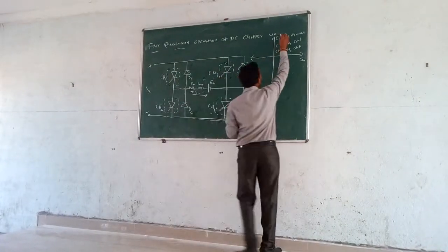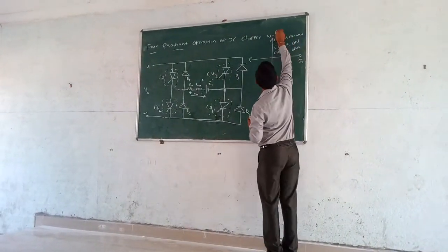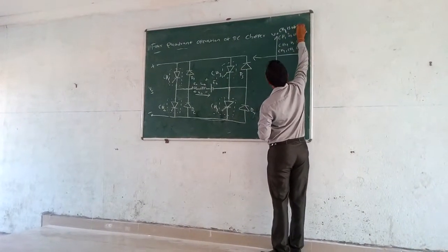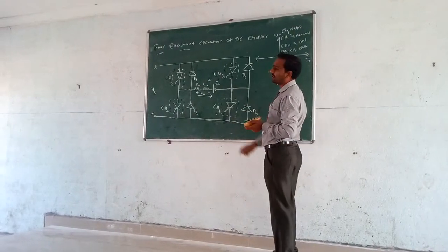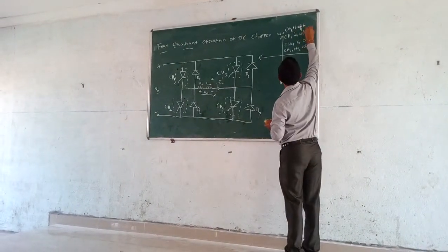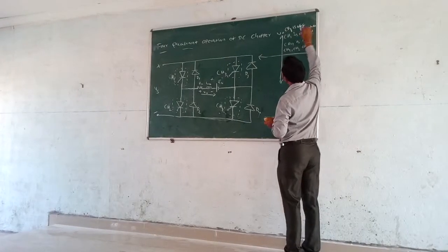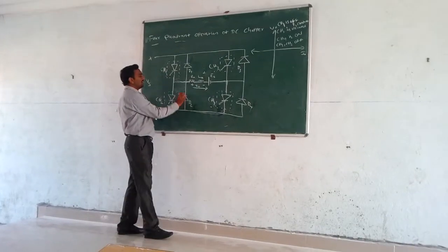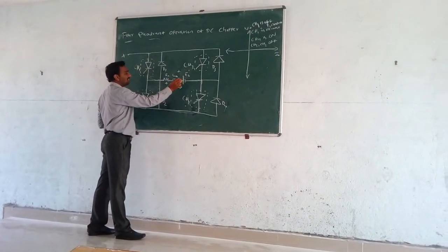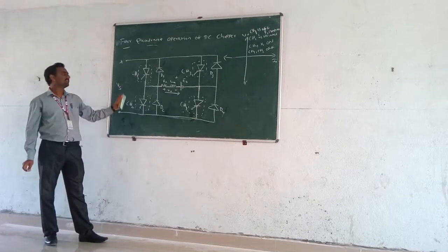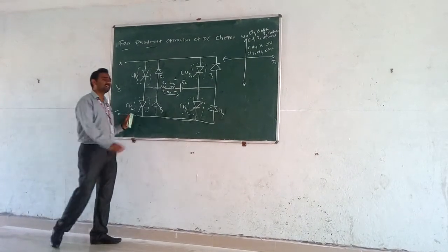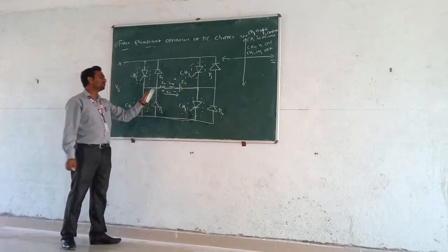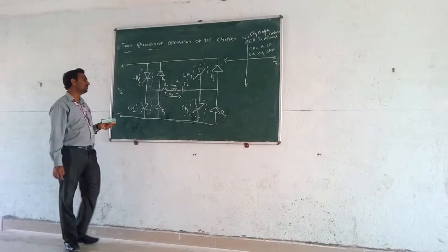So when CH1 is off, diode D2 conducts. At that time the supply is off and the back EMF acts as a supply, so the current flows from the battery through CH4 and D2. So the current flows in an inner loop.